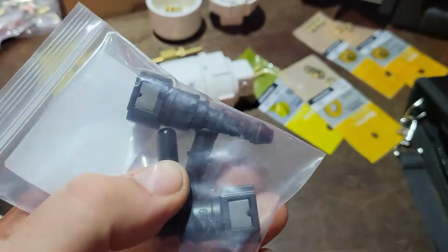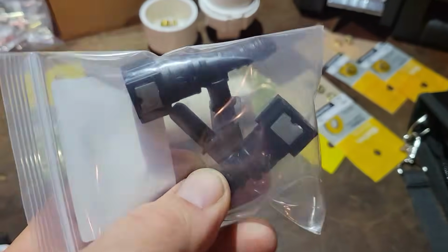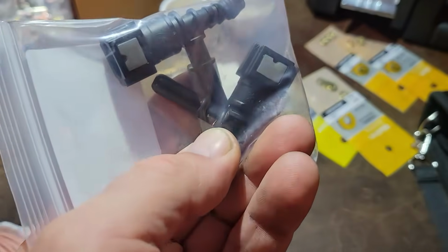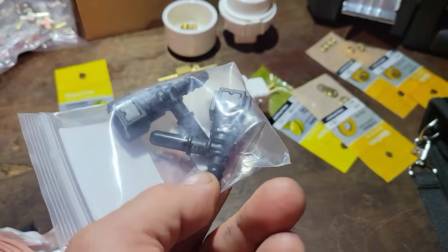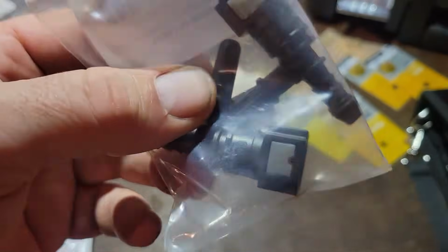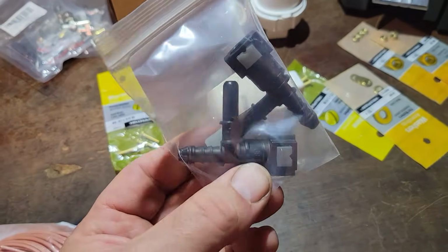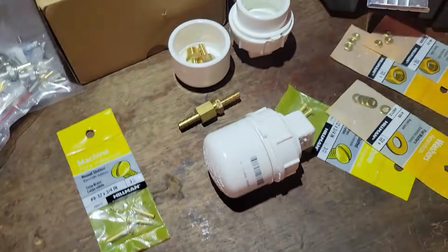You could make these without the tee, but you're only deadheading the pump. You're not technically deadheading it because the regulator's in the tank, but what you're doing is only getting the fuel pressure at idle. That's what you're going to get. Whenever you increase the RPM, you're not going to be able to test for conditions, just if it's getting pressure, which in a pinch could be helpful.